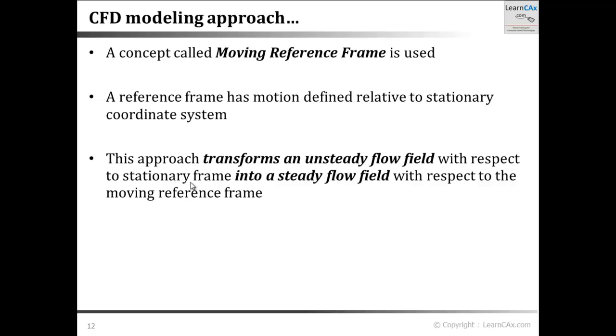Inherently, when we say that the blades are rotating, that makes the problem an unsteady or transient type of phenomenon. In order to simplify, this transient phenomenon is transformed into a steady state or time-independent phenomenon by using this rotating reference frame or moving reference frame. This moving reference frame is given a rotational velocity similar to the rotational velocity of the blades, and therefore, looking from the rotating reference frame, this becomes a steady state type of problem. So an MRF or rotating reference frame approach converts an unsteady flow field into a steady flow field.